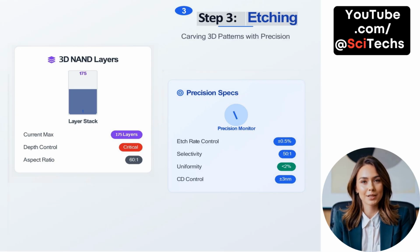Etching is a vital process in semiconductor manufacturing, especially for 3D NAND devices where structures are vertically stacked. Today's 3D NAND devices can have up to 175 layers. This creates a significant challenge in precisely carving through the entire stack while maintaining pattern integrity. The high aspect ratio of 60:1 makes etch depth control especially critical.